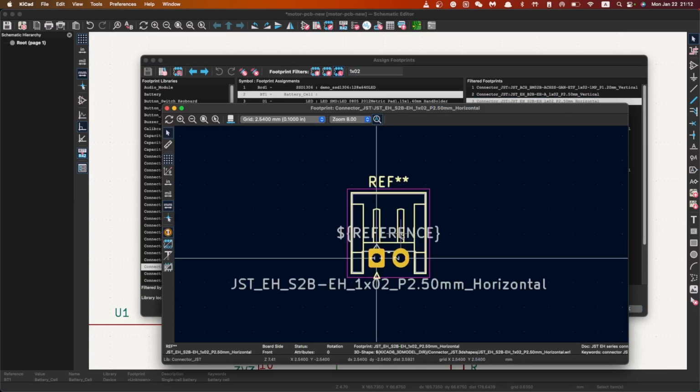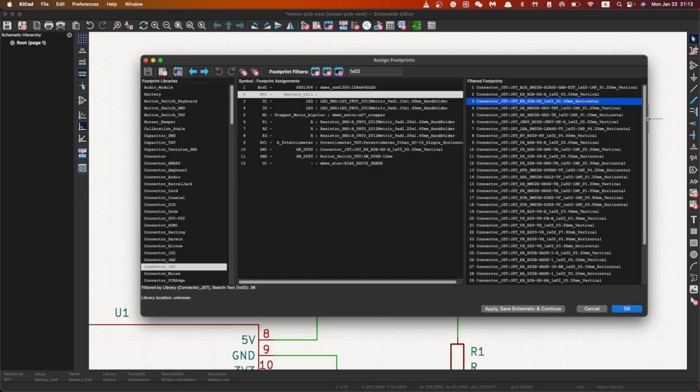And as we can see, even though this feels like a connector, for example, you can use LiPo or whatever connector or headers to connect this thing with, you can still connect wires directly to it, because this thing is nothing much but two pads or two through holes on a PCB board.